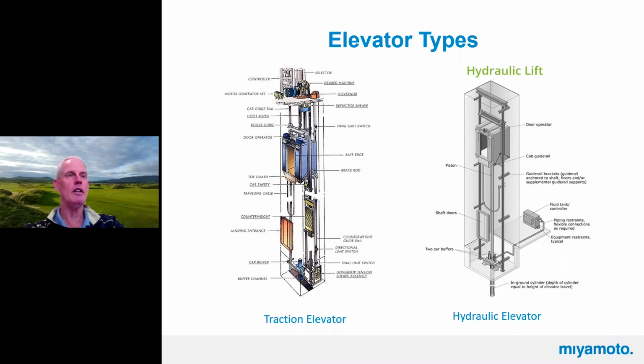So you typically need about 14 feet overrun height for an elevator. And if you have 11 or 12-foot floors, then obviously you need to pop the elevator up through your roof. You do a little pop-up, and your hoist beam has to be up there, or whatever supports it.